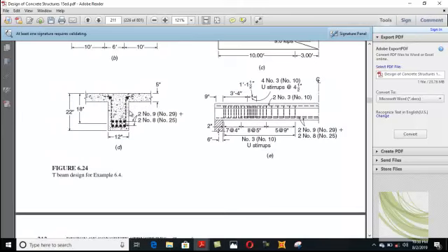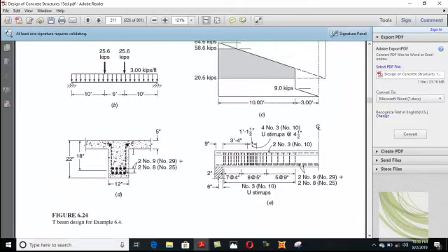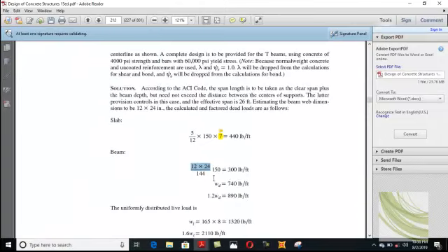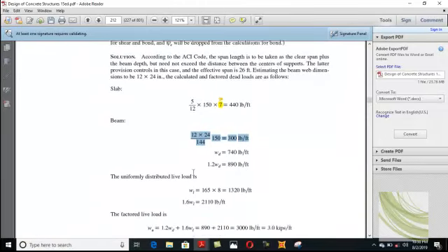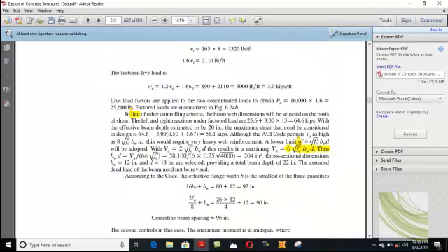So we can make this kind of calculation when we don't know about the width and depth. If you don't know about the width and depth of beams at the initial stage, you can assume higher values of width and depth and make the calculation. Calculation means you will determine the weights and then cross check it. If the values which you calculate from your shear criteria are less than your assumed, your calculation is okay. If they are greater, you need to recalculate the weights for the values which you get right now. Okay.